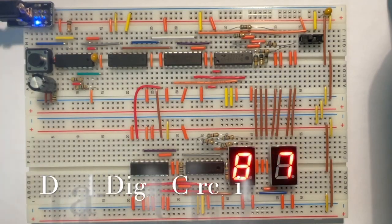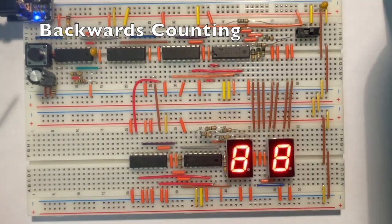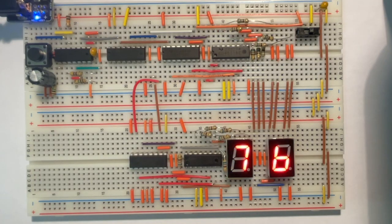Finally, a second 4510 and 4511 chip were added to create a dual-digit counter, allowing the circuit to count from 0 to 99. The carry-out pin of the first 4510 connects to the carry-in of the second, so when the first digit rolls over from 9 to 0, the second digit increases by 1. Just like the first digit, the second 4510 sends its binary output to the 4511 decoder, which lights up the second 7-segment display.